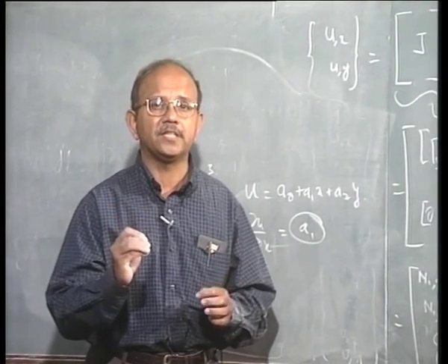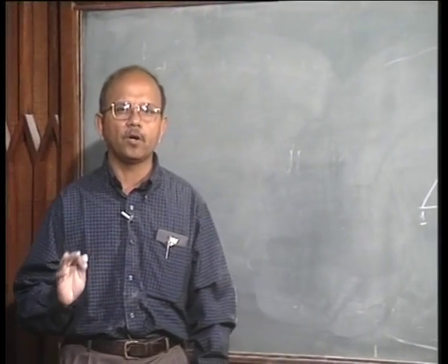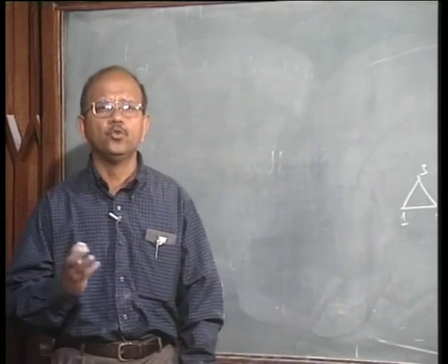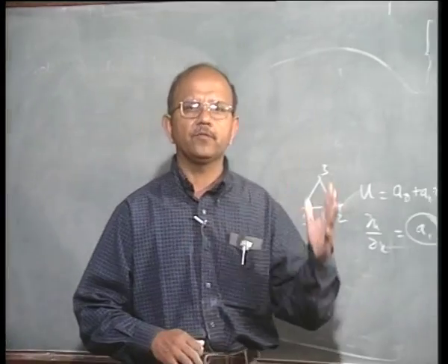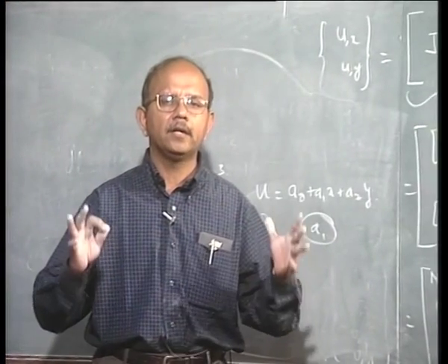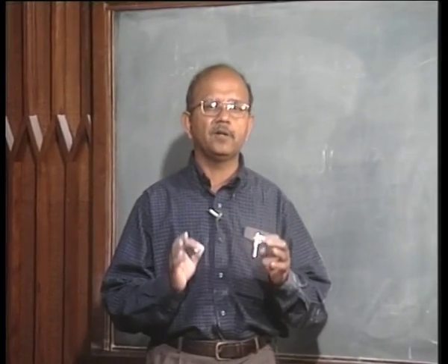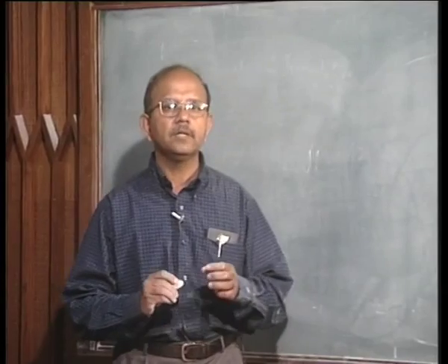So I am re-emphasizing it basically because I have found a lot of mistakes during modeling. Why are there a lot of mistakes? Because it is very easy to do what we call free meshing. Take a three-dimensional component, mesh it with tetrahedrons and just go ahead and finish the problem. But if you do not do a proper mesh sensitivity study as we did the other day, then you are going to be in trouble.